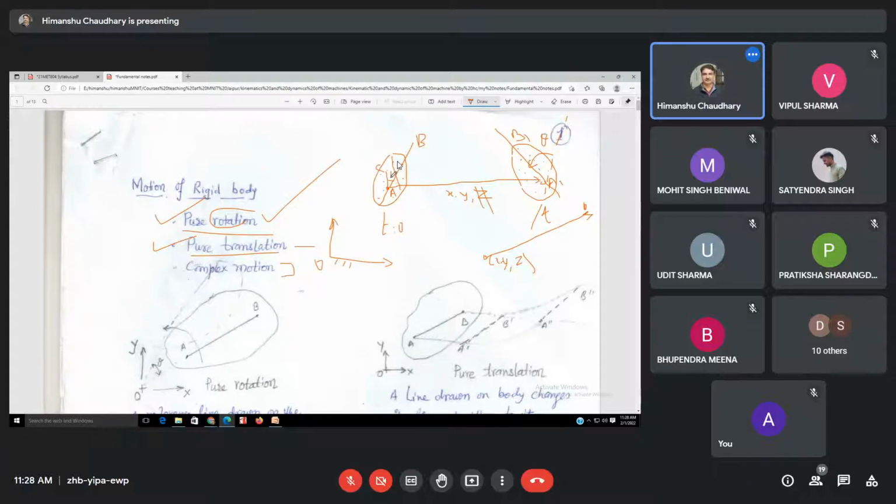This is angle alpha, because I know AB and I know AC, since this whole body is defined already. It is known, so angle alpha is known. This body is rigid, so the distance between points remains constant. So by knowing the coordinate of A and the length of AC, which is known by virtue of the body, I can find the position of point C.